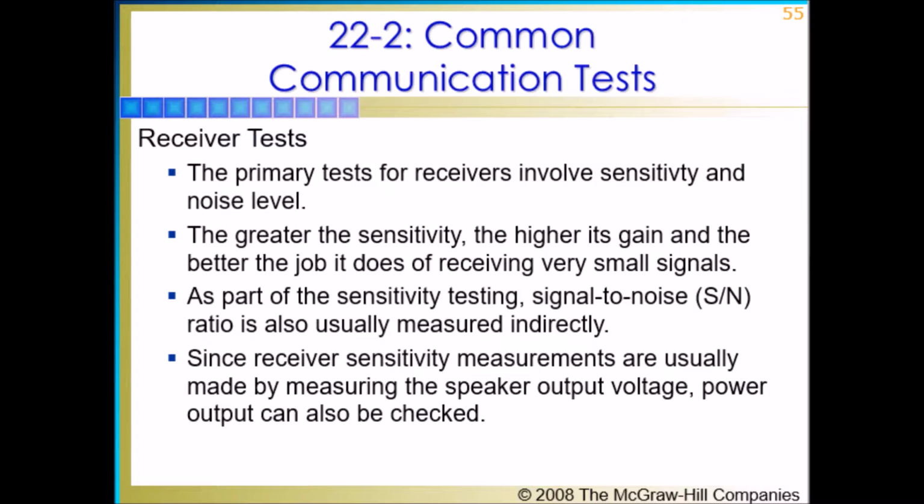As part of an overall sensitivity check, some receiver manufacturers specify an audio power output level. Since receiver sensitivity measurements are usually made by measuring the speaker output voltage, power output can also be checked if desired.